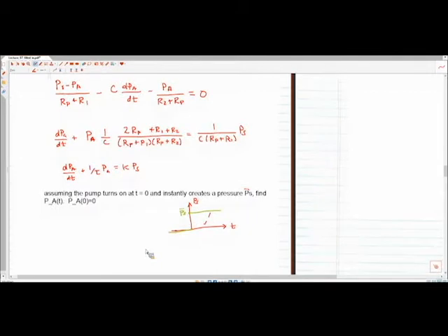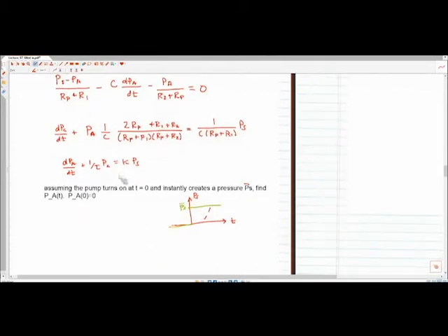So all initial conditions are equal to 0. That means to solve this, you can use methods that you will learn in your differential equations class, say sophomore year, or you can also use Laplace transforms if you want. And so we'd have then s PA of s plus 1 over tau PA of s. Sorry if that wasn't clear. I decided to use the Laplace transform method, not something you would see in your differential equations class. K PS bar plus u over s. Right.